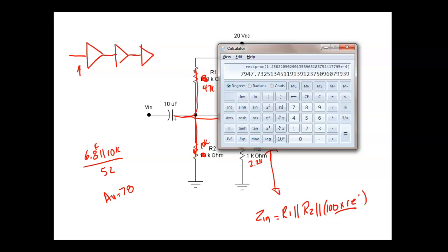Think about the antenna of your car out there. How much voltage do you think you get out of that thing? If you load that thing at all, you're going to get zero out of it. Your radio wouldn't work. So we want that antenna to feed an extremely high input impedance circuit. So we wouldn't use a bipolar transistor, or we'd use another type.